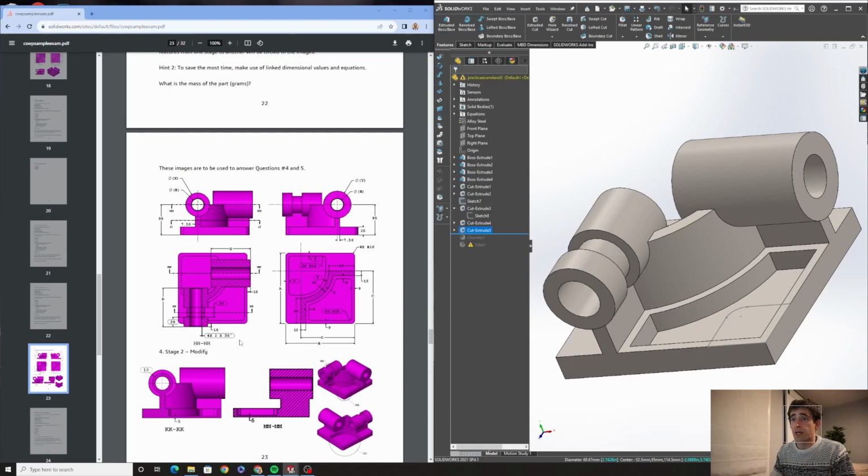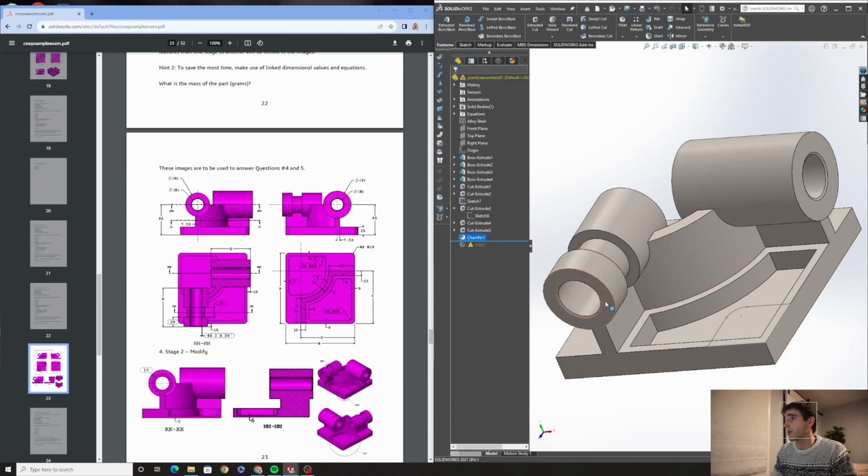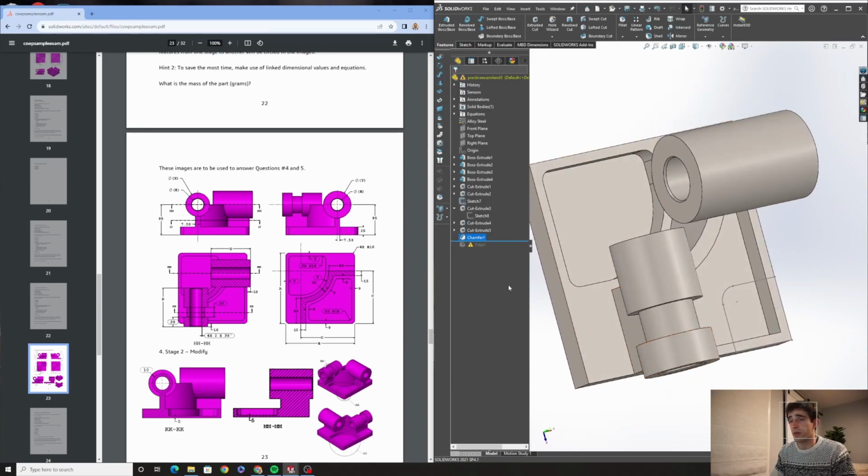Another good update that I would have almost missed right here is this chamfer. It's 4 by 2 by 30 degrees, so we'll have to fix that. This chamfer, instead of 30 here, so it's a 30-degree chamfer there. And here's this fillet we had from before. This is our radius 10 fillet.